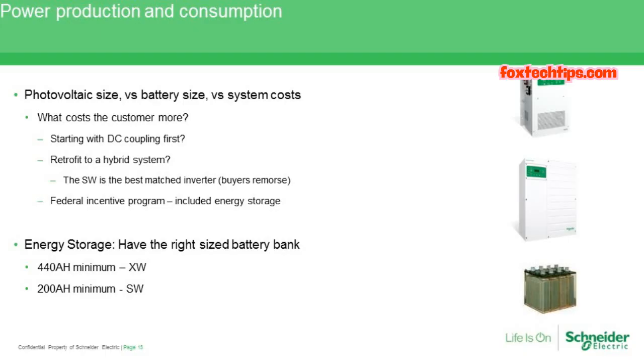But if they are looking for something where they want to have backup power and they want to be able to have some versatility for now and into the future, then doing DC coupling from the beginning, I would argue, makes the most sense. But there is always, of course, that option for AC coupling later on.